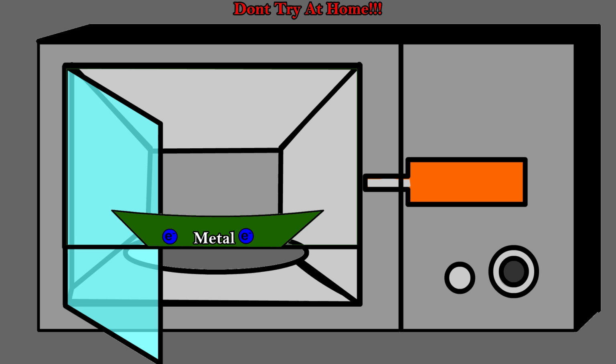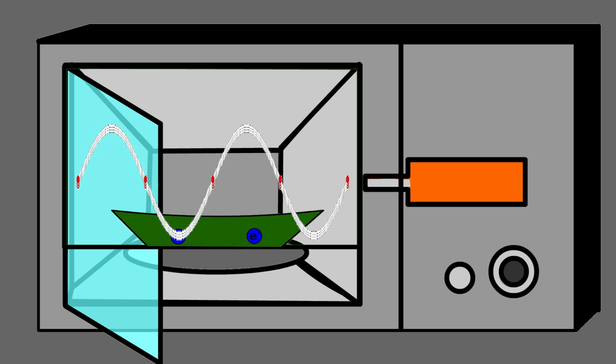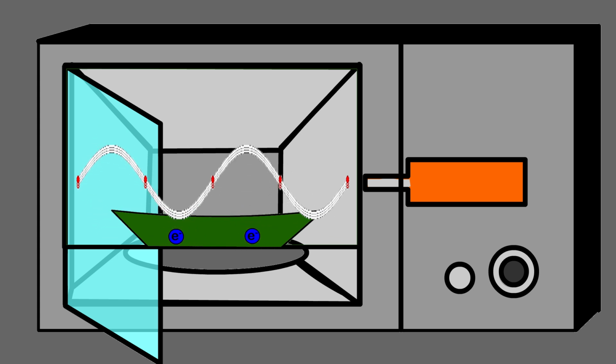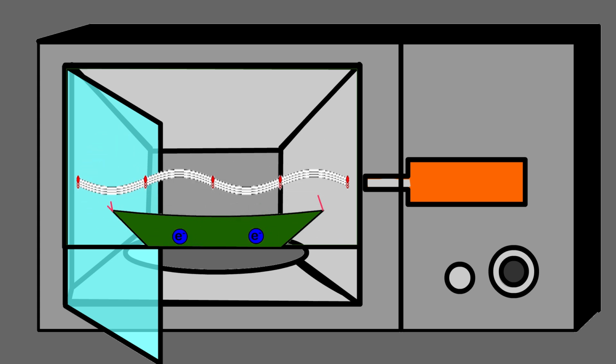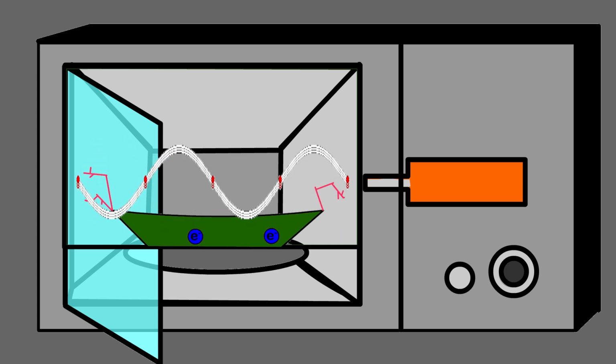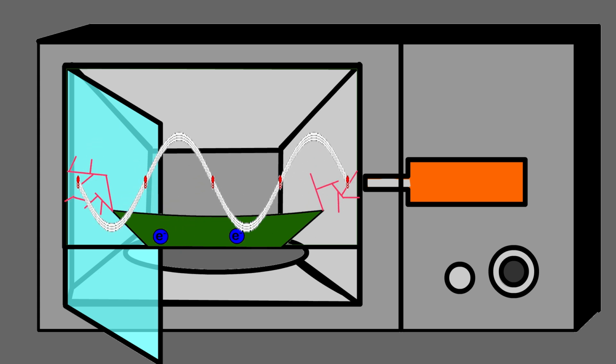Placing metal objects inside a microwave can be dangerous because metal surfaces contain free electrons. The electric field of the microwaves moves these electrons, generating a high-frequency current. If the high-frequency current cannot flow smoothly on the metal surface, energy accumulates at certain points, leading to ionization and spark formation. The air around the edges of the metal can become ionized, creating sparks that may damage the microwave oven. For this reason, metal objects should not be placed inside a microwave oven.